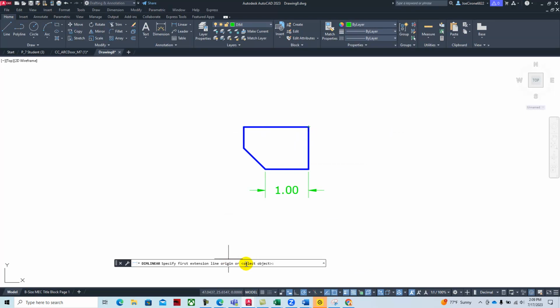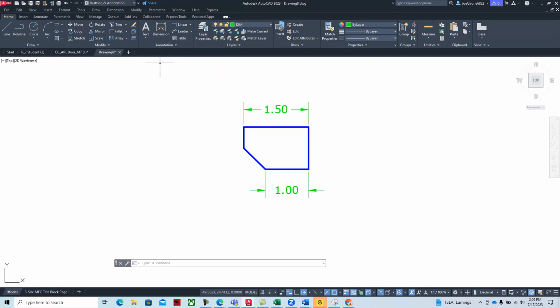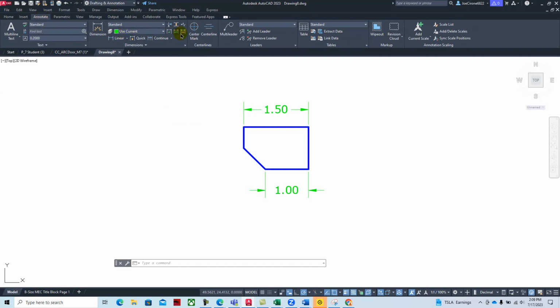And it seems to be glitching because it says select the object, but when I'm selecting it, it's going for the endpoint. So I'm just going to go with endpoints and just place that on there. And so as we place the dimensions on there, it's automatically placed. And then things like the dimension style and things like that are associated within the annotation and the dimension styles area. You can place dimensions either on the Home tab in the annotations with these different dimensioning, or you can go to the Annotate tab where they have more dimensioning in multi-liters and things like tables and things like that.